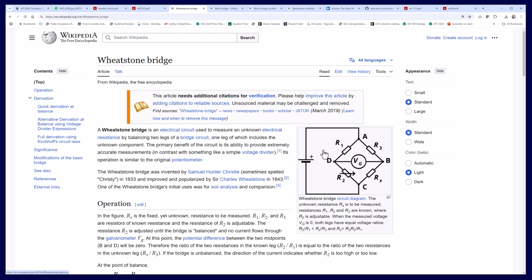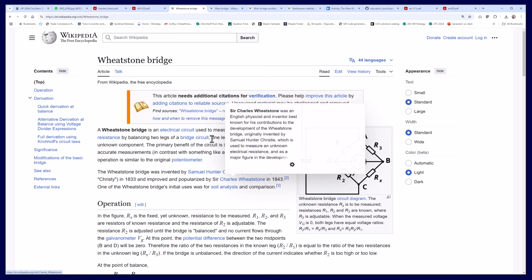And what we do is we place a voltage across the top and bottom of this electrical bridge here. And then let's say that some physical phenomenon like temperature or pressure or torque causes one or more of these resistors to change. I can measure the difference between points D and B here on the circuit and get an actual signal out of this.